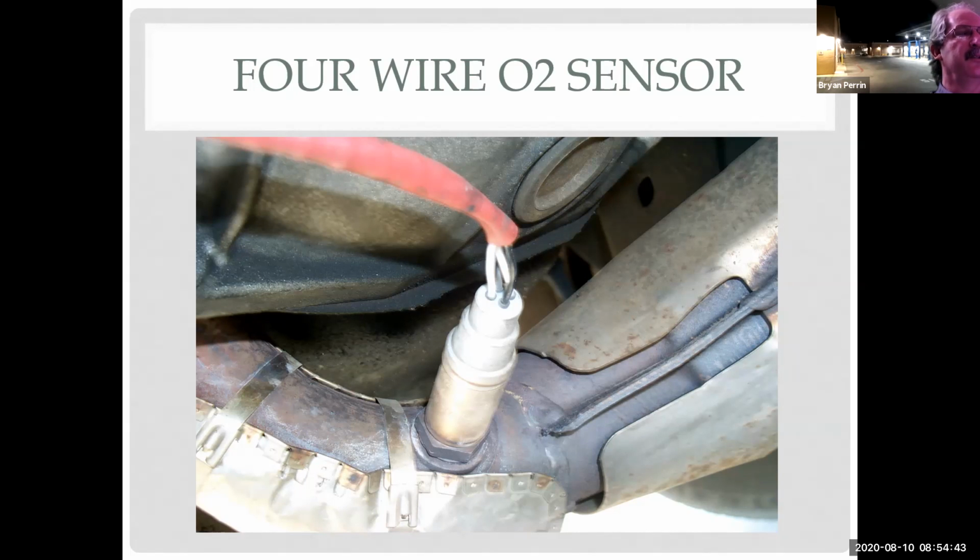So again, this is a 4-wire sensor. They do sell some universal sensors where you're supposed to cut the 4 wires and splice them into the factory connector. Never use those. That's not the right one for your car.